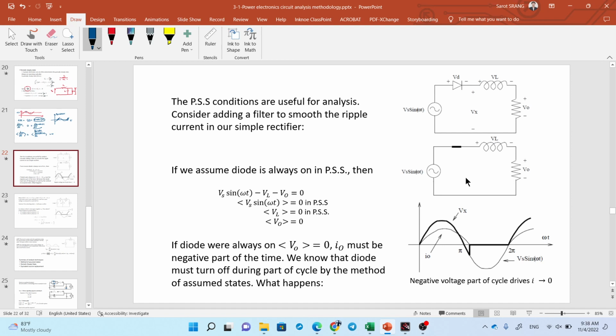First, we apply Kirchhoff voltage law on this loop. We put the terminals positive, negative like this. So you have the positive of the source, and then this one minus to plus, you assume it to be positive, and then this one plus to minus, then it must be negative. Here plus to minus, also negative.